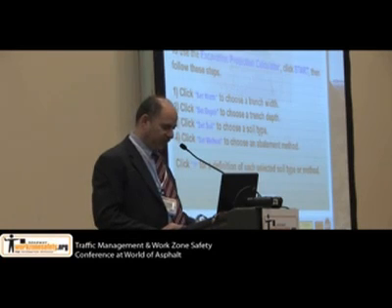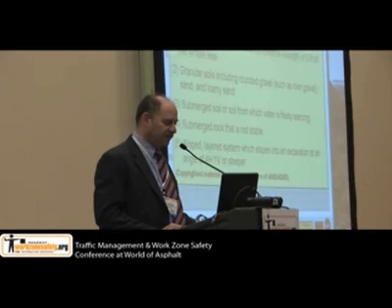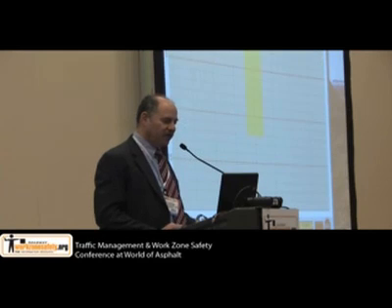So if we click the Start button, for example, we can set the width of the excavation. Say we make it 4 feet wide. Say we make it 12 feet deep. Okay, and we set the soil type. Say it's type C soil. And you can click this little question mark to see what that means. And then you set how you're going to protect people.